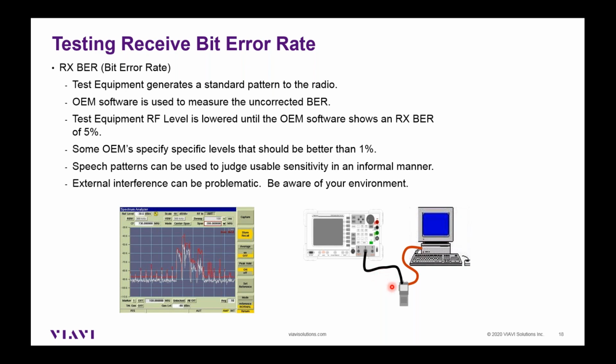I've seen cases where an adapter on the radio wasn't tight and it was loose. Signal can get into that. And what I'm seeing on this analyzer, these are actually pretty strong signals, like minus 40. It would cause the radio to fail the receiver sensitivity test. I can take our equipment to a trade show. A receiver will never pass a receiver sensitivity test in that environment because of all those strong signals in the area. So some solutions would be to have some type of case that you can put the radio into, or a screen room or something like that to shield yourself from the outside world.